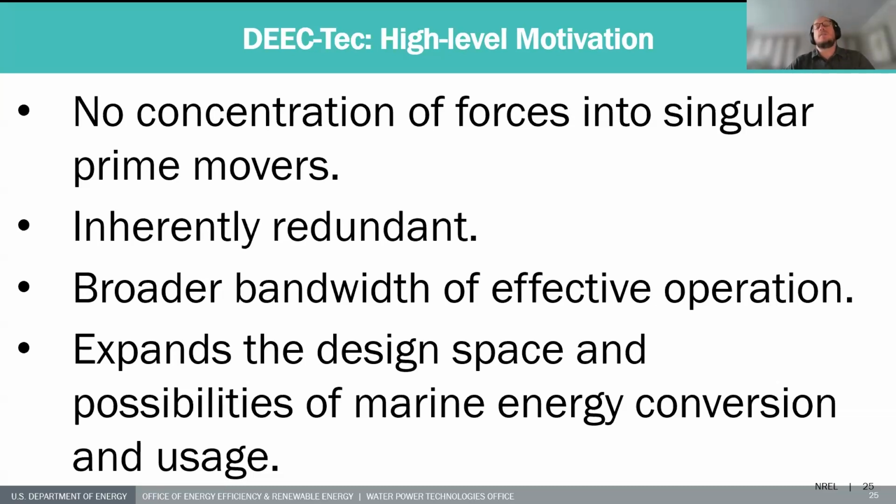By virtue of creating a wave energy converter with multiple bodies and multiple individual distributed embedded energy converters, you have multiple degrees of freedom, multiple eigenmodes. You immediately are accessing different wave periods of the ocean wave energy resource that you wouldn't otherwise be able to access. So you have a much better ability to capture across different seasons of ocean waves, different types of ocean waves, than what would otherwise be possible.